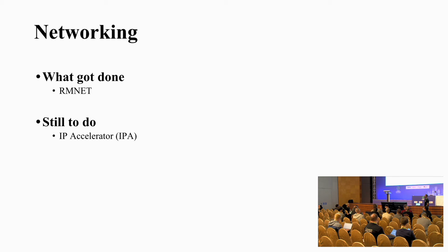The other problem that I've seen a few times with the way to load firmware into devices on the Qualcomm chips is apparently that the firmware interface is not particularly well defined to what kind of addresses it takes. It is well defined. It's just more convenient to use the DMA alloc. So it takes a physical pointer. I thought there was now a case where it doesn't, where it takes a DMA address that might be an IOMMU. No, it takes a physical address, the SCM interface.